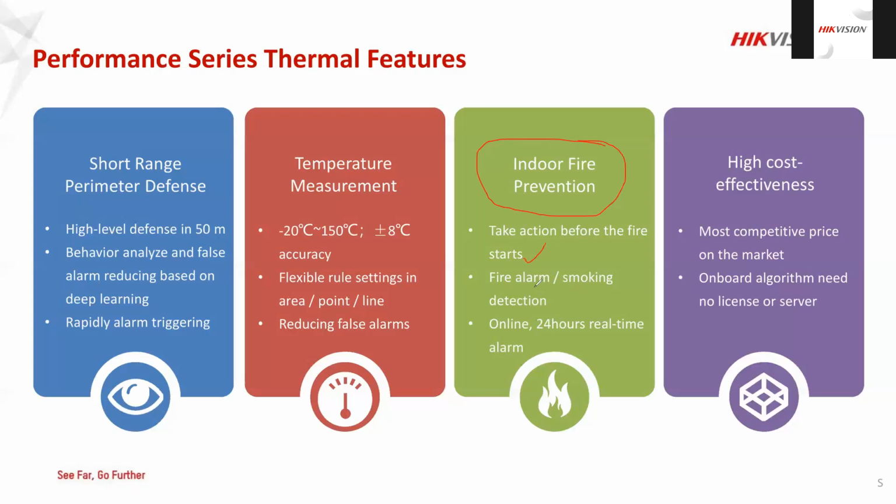We can take action before the fire starts. Not only do we have the fire alarm, but we now have smoke detection as well. If there's smoke, the video analysis can generate events for smoke too. We have a 24/7 real-time alarm, and we can deliver it in many ways, not only as a siren. We have a flashlight. We can deliver it to your mobile through our Hik-Connect app, or to your monitoring station through HikCentral or iVMS-4200. You can even link it to one of our industry leading alarm panels and receive it as a phone call. There are many options for configuring this kind of fire detection or prevention system. We will discuss those details in the upcoming slides.